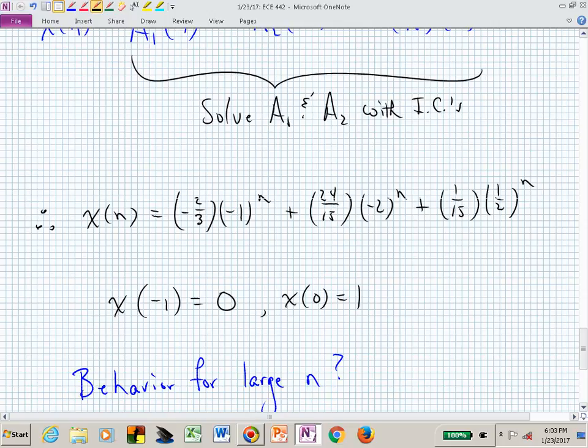And where they are would influence the frequency of that oscillation. Now that we're at -1, what's the frequency of that? Positive, negative, positive, negative, positive. That's pretty high, isn't it, as a frequency? We'll find that -1 is a high frequency signal in a discrete time system, or when we have roots at -1.